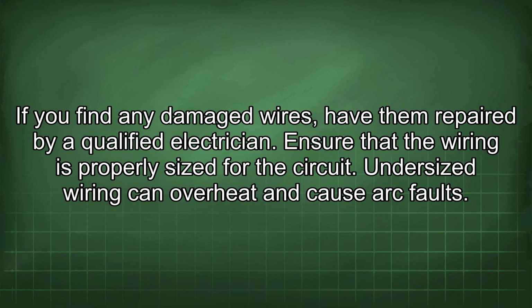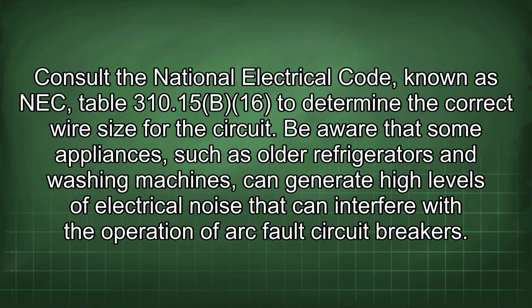Ensure that the wiring is properly sized for the circuit. Undersized wiring can overheat and cause arc faults. Consult the National Electrical Code, known as NEC Table 310.15(B)(16), to determine the correct wire size for the circuit.